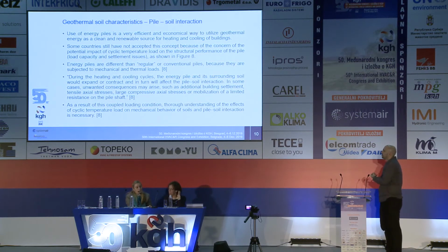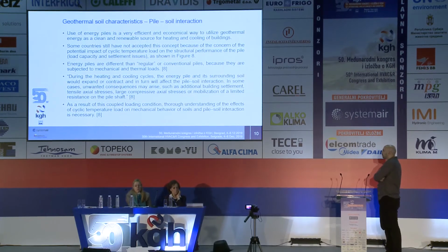Energy piles are different from regular or conventional piles because we have an additional load, which is mechanical and thermal load. During the heating and cooling cycles, the energy pile and its surrounding soil would expand or contract depending on the type of the load, and in turn it will affect the structure-soil interaction. As a result of this coupled loading condition, it is necessary to thoroughly understand the effects of cyclic temperature load on the mechanical behavior of soil and pile-soil interaction.